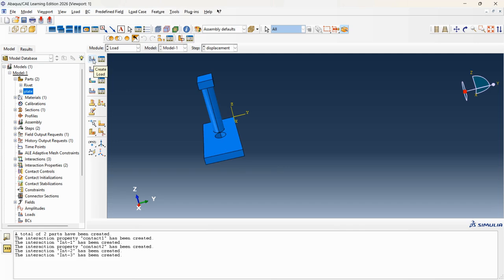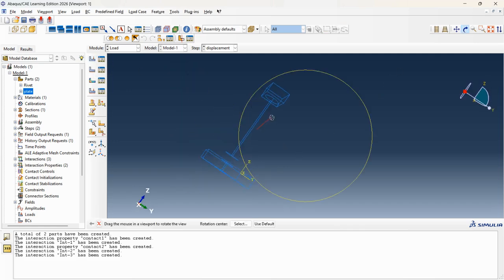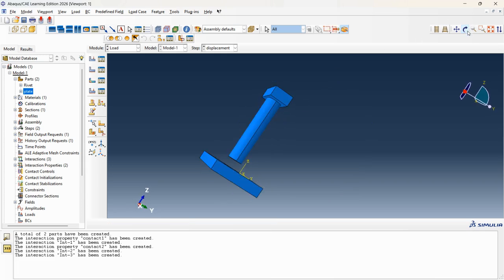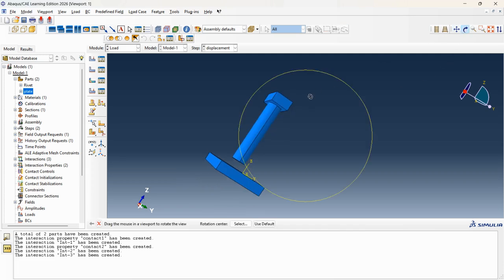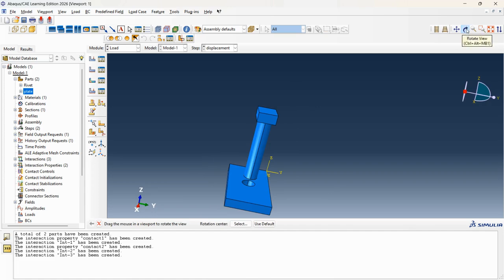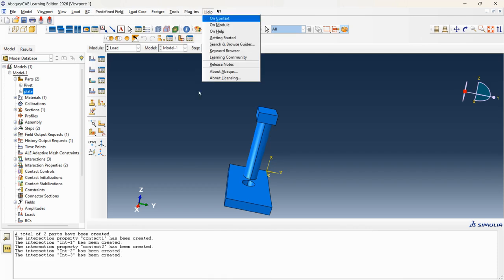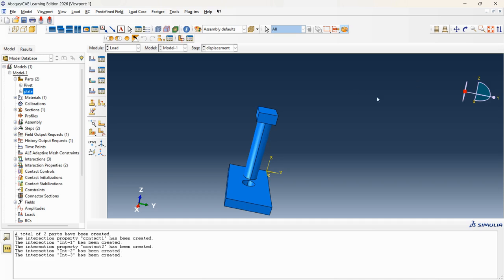So I'm not gonna apply a load, but a displacement. Yeah, and I measured this. I know it's about 78 millimeter, I mean, from this edge to the plate. Okay, you can also measure it here on tools. You go query and you search for the measure tools or the distance tool, and you can measure the distance, but I know it's 78 millimeter.